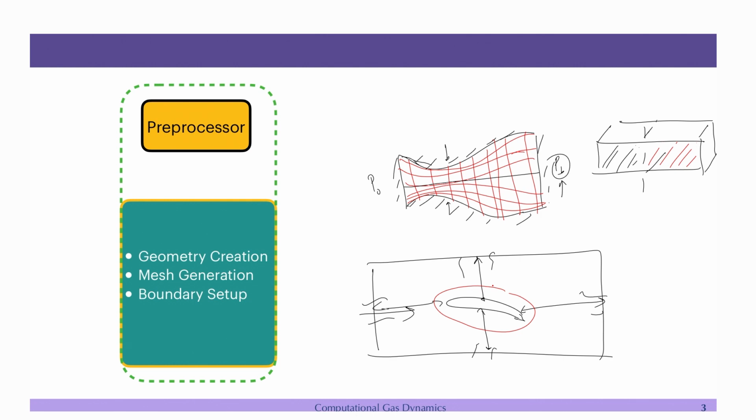So, it is a balance. In fact, when we discuss LES or DNS, which are advanced simulation methodologies, you want to make it as small as possible. At the same time, you have to use the boundary conditions intelligently, so that no waves come in and corrupt the solution near the aerofoil. So if you are getting a geometry, you have to clean up the geometry, decide how far you want to keep the external boundary, and then apply the boundary conditions here.